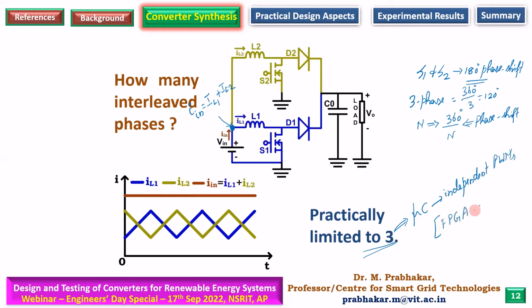So you can use these FPGA processors and then you can have, quite literally, n number of PWMs. This is possible. Still, I'm telling you, if you don't want to waste the switch, then you go for microcontrollers. Take a simple microcontroller and then you program it, get 2 pulses with a phase shift of 180 degrees and then it works. That's the way it works.